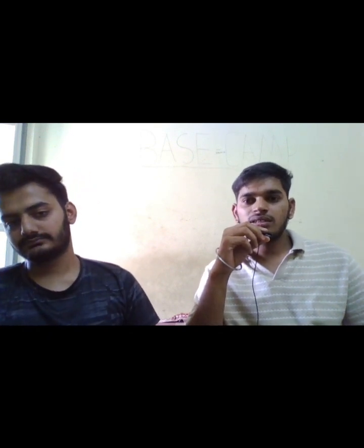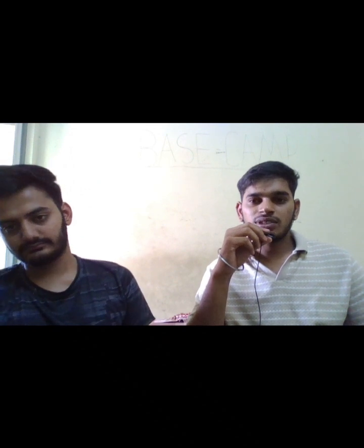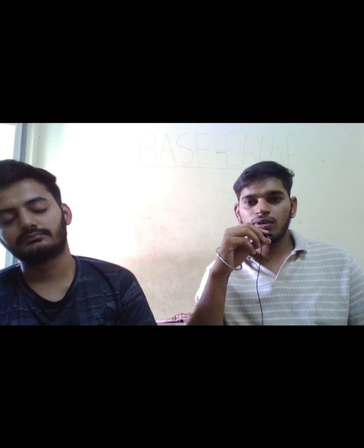Now further we will be discussing interpretation of dimensionless numbers. Number one, Reynolds number, which is inertial forces upon viscous forces. Inertial forces are rho v naught L naught and viscous forces mu. So Reynolds number is equal to rho v naught L naught by mu. We will see the first case, when Reynolds number is less than 1, the viscous forces dominate, which means creeping flow, that is laminar flow. Second, Reynolds number greater than 1, inertial forces dominate, which means turbulent flow.